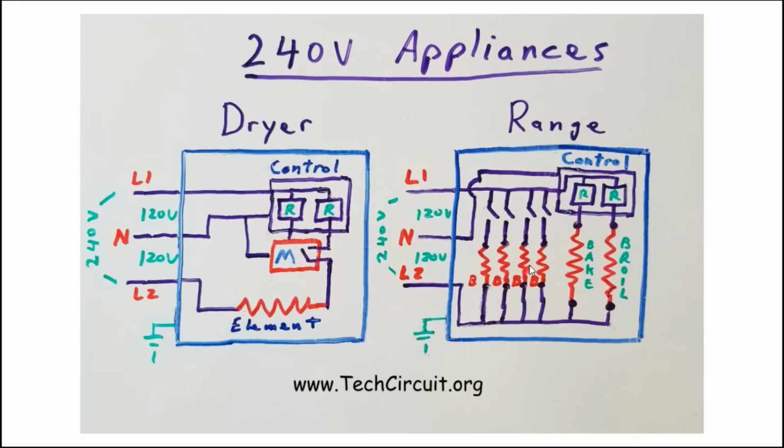Now, for what is typically 4 cooktop burners on an electric range, you have individual switches. These aren't just switches, they're actually called infinite switches, which control the amount of time that the voltage is actually passed on to these elements. But they're just representative switches here for simplicity. And those circuits go from L1 through the element and back to L2 for each of these circuits here.